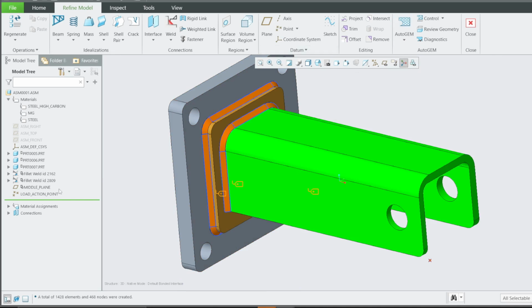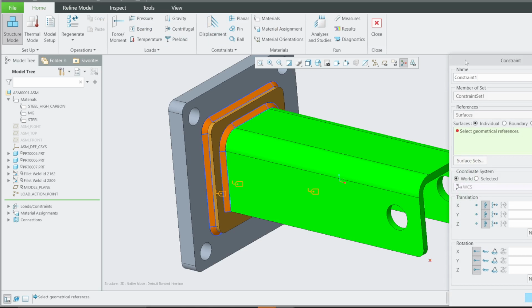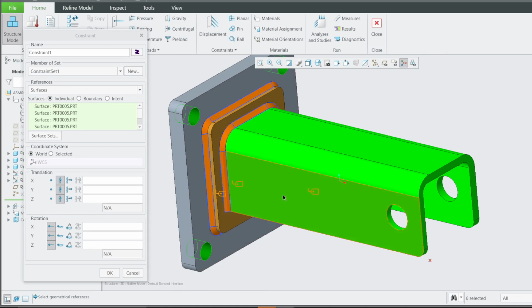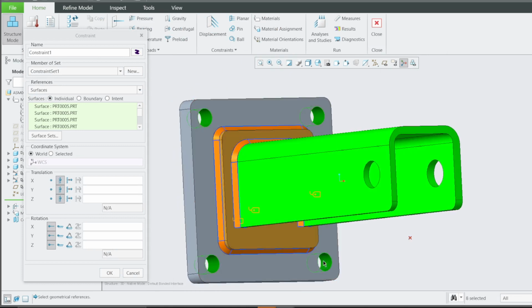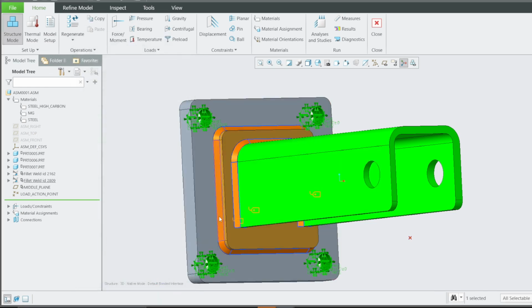And then, if you go home, this placement, we need to fix these holes. Therefore, if you go to the references here, I'm going to select a surface. I'm going to fix translation, fix these surfaces here. For the one, I can select individually, pressing Control. This will be the mounting point. Therefore, we're going to assume we have fixed these four surfaces like that.